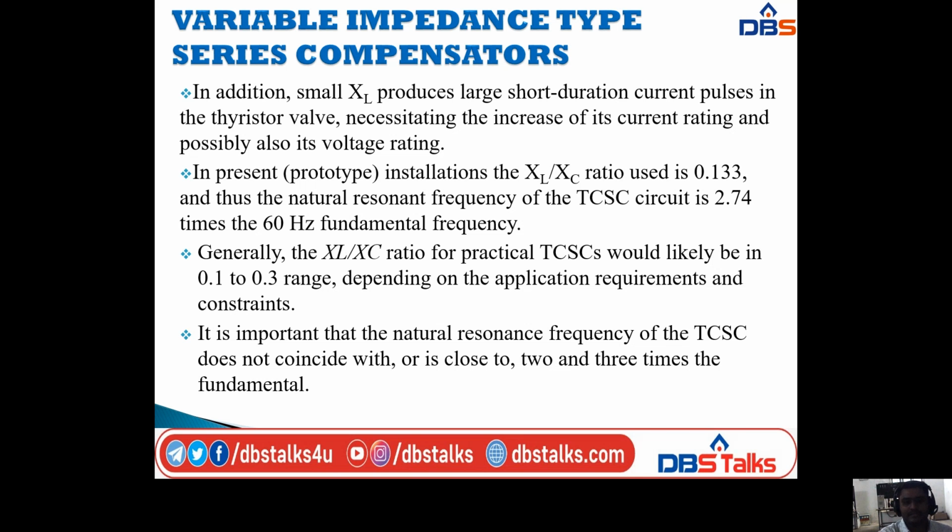It is important that the natural resonant frequency of the TCSC does not coincide with or is close to 2 and 3 times the fundamental.